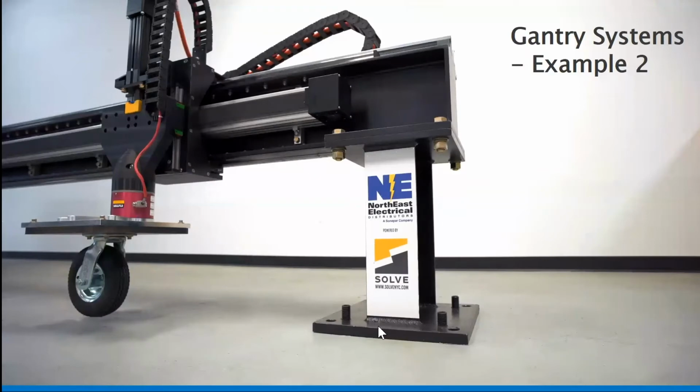All right, so that's another example, fairly recent. What you see here, you have two Tolomatic products on that machine you might recognize. One is an MX actuator, belt drive, non-guided, and that's the one across, the long one. And then the vertical actuator is an RSA series rod style actuator, screw style. And you can see here, both of those actuators were complemented with linear rails to absorb the type of load that the system was required to handle.